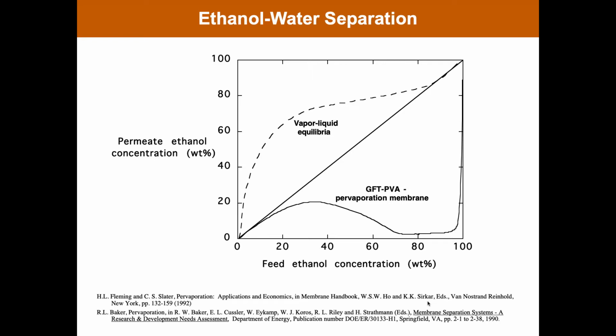Ethanol, as you may know, is hydrophilic. In fact, it's almost hygroscopic. And so as the ethanol is transported from the point where it's made to the refineries and then ultimately to the blending process, there are opportunities for it to pick up water. And so you have to purify it above fuel grade standards so that it doesn't drop below the fuel grade level by the time it gets to the folks that are going to do the blending. Otherwise, they send it back.